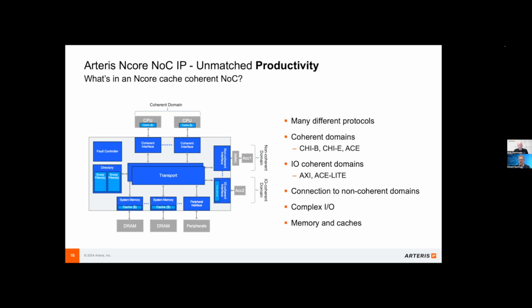Absolutely. I mean, the key point here is efficiency. We're talking about the point of coherency, moving on chip. It needs to actually be focused and the data efficiently moved and shared between the devices that need to move and share it. And every time a device accesses a cache, that can be filtered. So every single access doesn't need to be communicated to each individual device itself. It can actually be filtered out, and the device only needs to get the transactions it's really interested in.